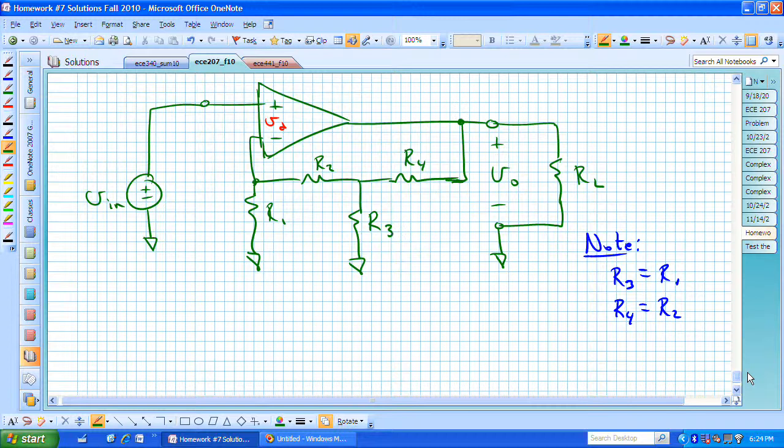to do the analysis. I'm going to also start to label some of these currents that I have. Here's I1, here's I2, I3, and I4. I will label those. And with respect to the summing point constraint, if I need to refer to those, let me call that the current going into the positive or non-inverting terminal. Here is I sub minus, and we know those are actually 0 from our summing point constraint. Maybe I'm getting ahead of myself. Let's now talk about our solution.